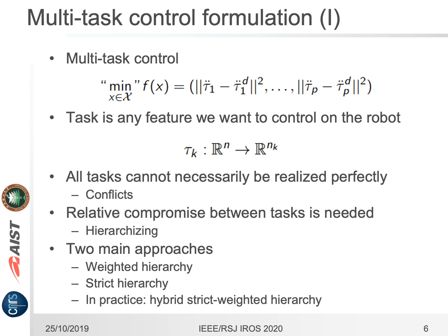Each task would then require a finite set of robot resources that are the sensors and the joints, whose availability could eventually not be fulfilled for each task. In this latter case, the tasks are said to be conflicting. A compromise is then needed that is usually resolved through prioritizing the tasks in a strict, soft, or a hybrid fashion.